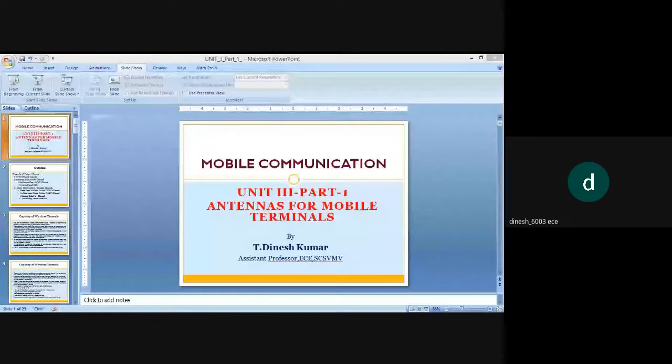So next is the additive white Gaussian noise channel capacity. Here, reliable communication at a rate of R bits per symbol means that one can design codes at that rate with arbitrarily small error probability. In order to achieve reliable communication, one must code over a long block, to exploit the law of large numbers to average the randomness of the noise.